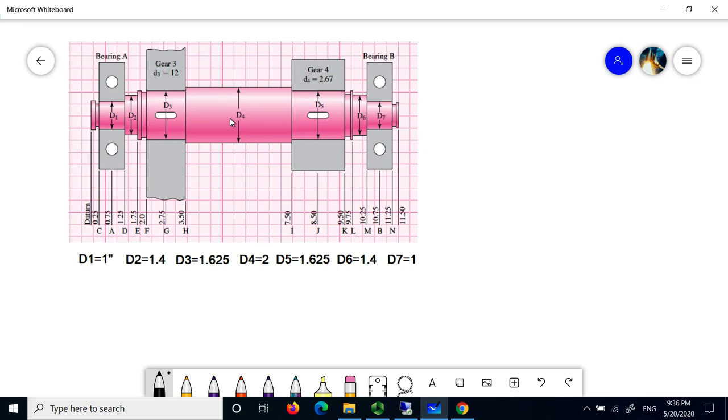As I said in class, in layouts, most shafts you see have the thickest part at the center, and then getting closer to the bearings it's going to get thinner. So the example from Shigley's book, we went through and we found diameters based on stress analysis. So here are the results. I summarize the results here and I show you the diameter at different points of the shaft.